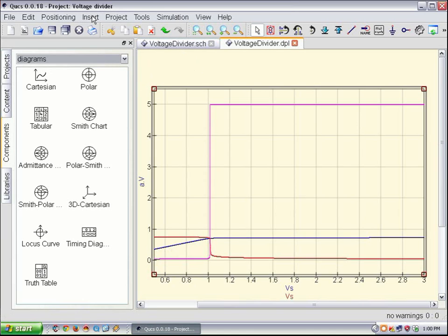But when the signal is at 1 volt, you can use a marker at this point. So at this point, A is 0.703. So the input voltage has to be 703 millivolts for the base of the transistor to give you 1 volt at the output, or give you a logic 1, or a logic high at the output.